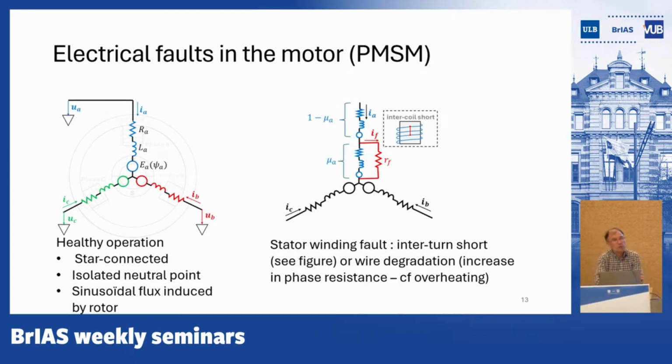I will not bother you too much with electric motors, but just to tell you that we consider a star-connected motor with insulated neutral point. And we consider a situation where a sinusoidal flux is induced by the permanent magnets of the rotor. One of the sorts of faults that we will consider is inter-turn short circuits within a coil.